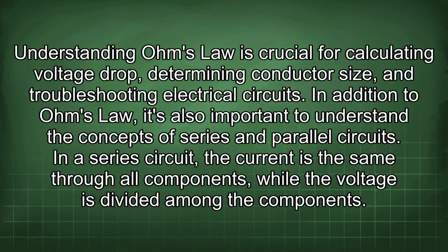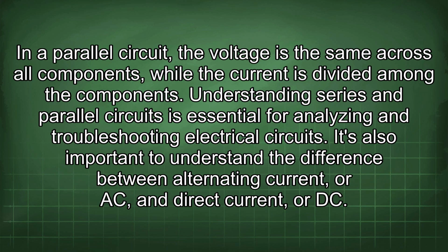In addition to Ohm's law, it's also important to understand the concepts of series and parallel circuits. In a series circuit, the current is the same through all components, while the voltage is divided among the components. In a parallel circuit, the voltage is the same across all components, while the current is divided among the components. Understanding series and parallel circuits is essential for analyzing and troubleshooting electrical circuits.